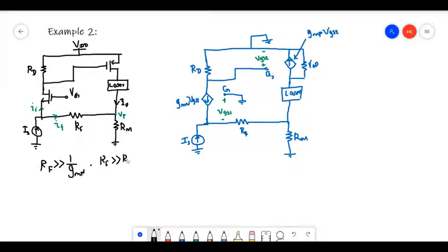So actually, even though this is not given, we should know that because we are doing a series sampling, Rm resistor should be small, and since we are doing parallel mixing, RF has to be large, right? So first of all, we need to draw the small signal model.